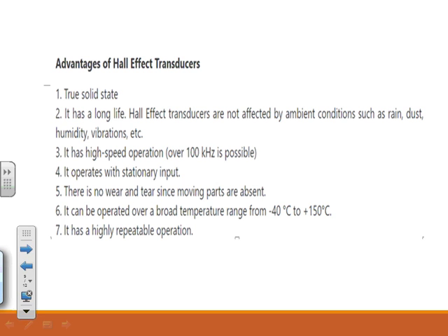Then we can see the advantages of Hall effect transducers. First one is that it is true solid state. It has a long life because Hall effect transducers are not affected by ambient conditions such as rain, dust, humidity, vibration, etc. It has high speed operation.